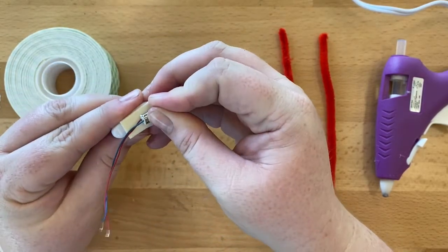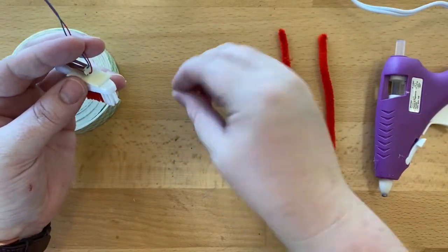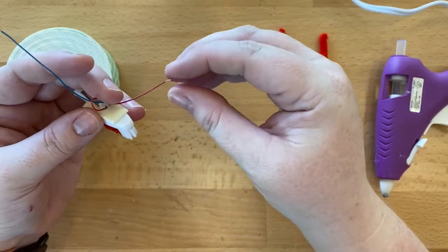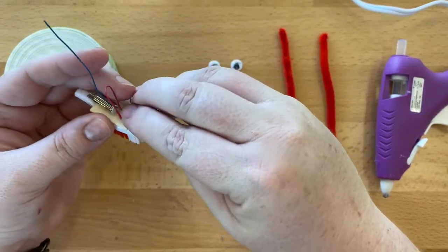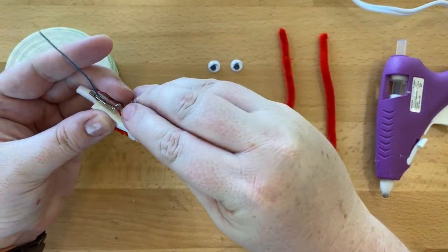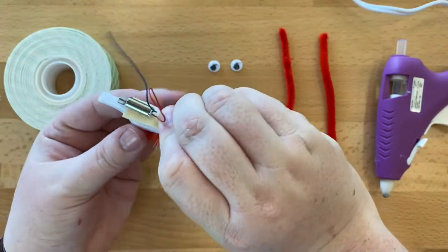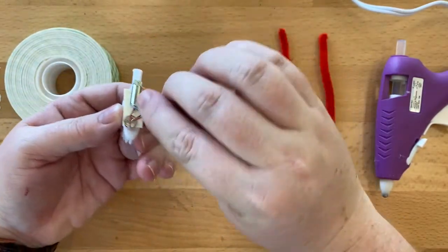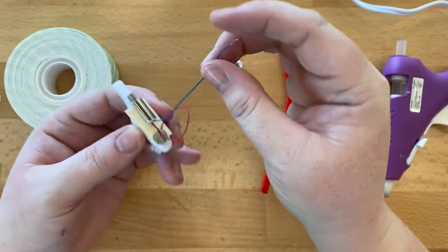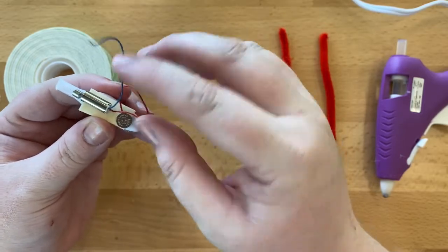Our next step will be placing the battery. First, you want to make sure that your wires are facing towards the front of your toothbrush. Then, take your red wire and carefully place it onto the foam tape. Press it really firmly to stay. Then, take the button battery and place it on top of the exposed wire. Press firmly so the battery does not move. You can test to see if it's working by placing the blue wire on top of the battery. If your motor spins, you have a good connection.